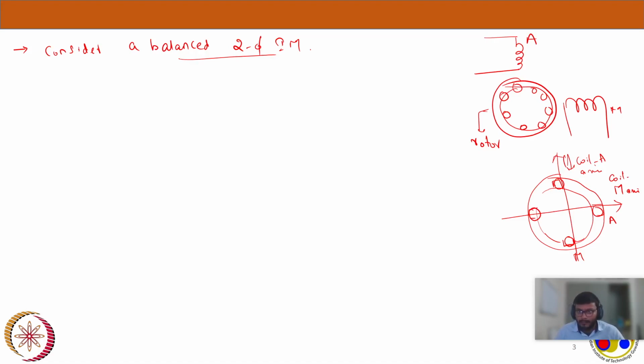That's the principle of the machine. We saw it in the three-phase also. Whenever we supply three-phase windings with a balanced three-phase current, a rotating magnetic field will be produced. Now the same holds for a two-phase machine as well. So let's say the currents are like this. Let small im be the instantaneous current flowing through the winding M. Im is the RMS, and Im max is the maximum current. So im equals Im max cos omega t.